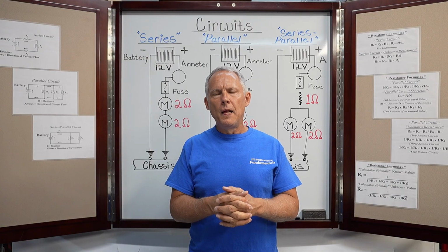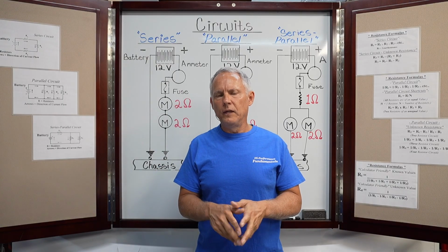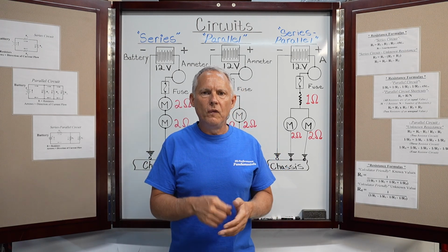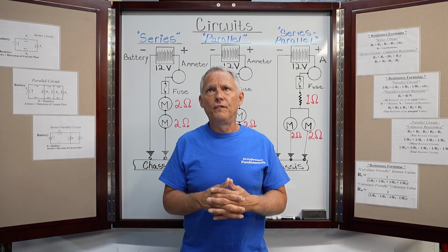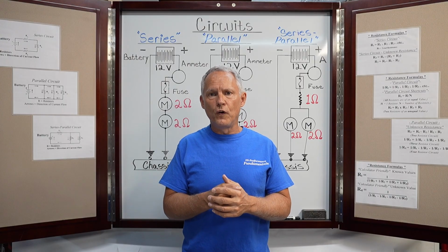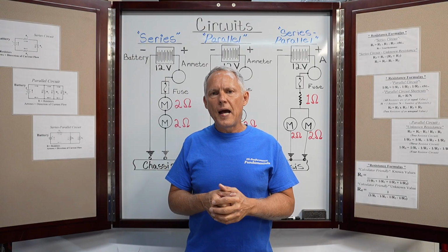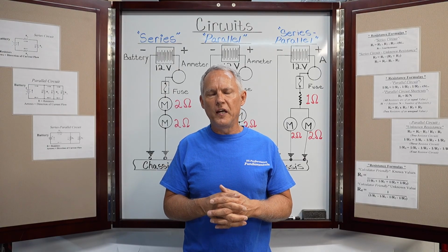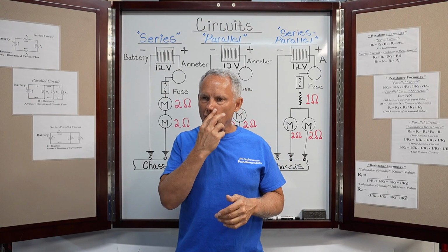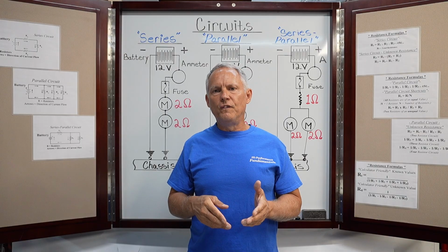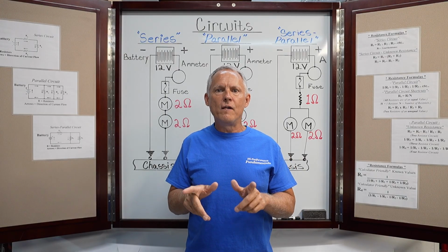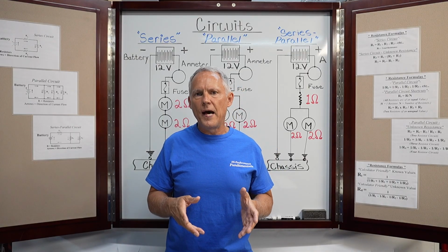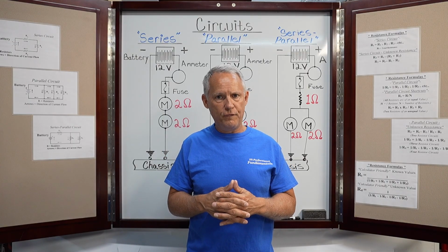That's pretty accurate. It may be slightly different than that, and like I said, refer to the manufacturer's specifications for your application. The 6-cylinder I gave, let's see, that was 34 to 38 degrees. Also fairly accurate. Like I said, always refer to the manufacturer's specifications. But on the 4-cylinder, although what I had said was 52 to 56 degrees is a decent average range, and although that is accurate for some models, what I found was that on certain models, it's way off.